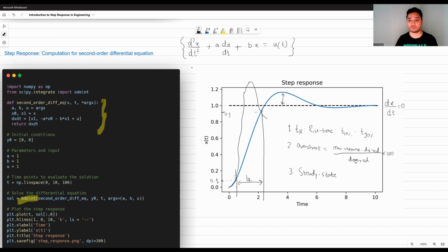An equivalent of that would be to look at what the steady state error is in the step response. We want it to reach the value 1, but it may reach some other value at steady state. Here YSS is the steady state value, and this would give us a measure of the steady state error. So we would want this error to be as low as possible.